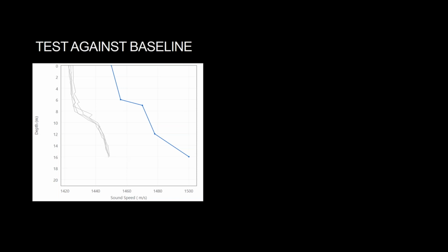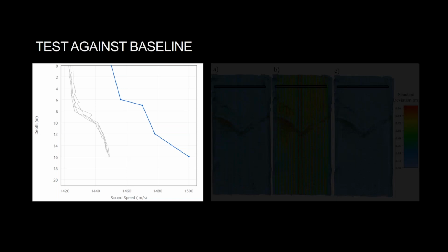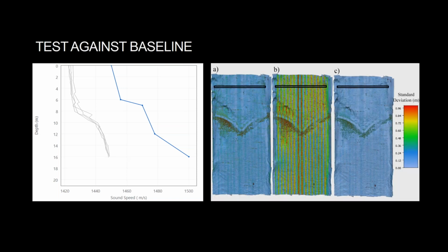So we're really stretching it to see how far we can make the data, which was in a good state when we got it, and see, let's make it purposely bad and then see if we can recover from it using the TU Delft algorithm. And that's what this image shows. This is an image straight from the paper that we worked on that supports this talk. On the left, you see a terrain model showing this, and this again is color-coded by the uncertainty of the soundings in the grid. So showing the raw data as processed with the raw sound speed profiles, and you see for the most part it's a nice light blue. There's good agreement between the multiple survey lines up and down through that area.